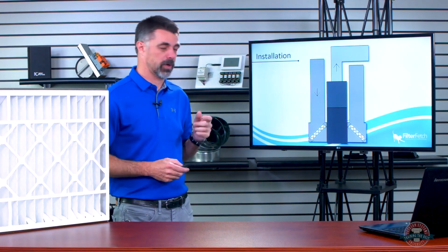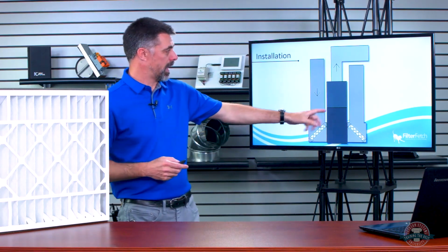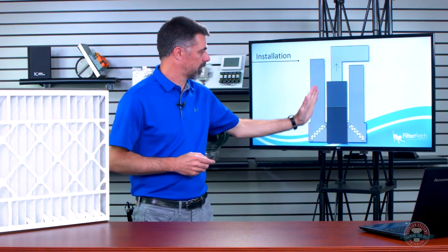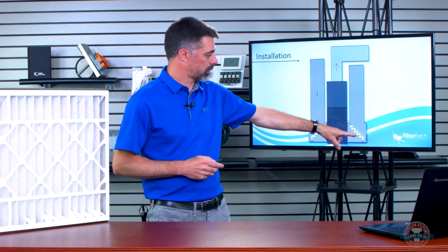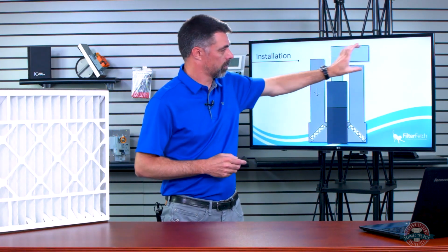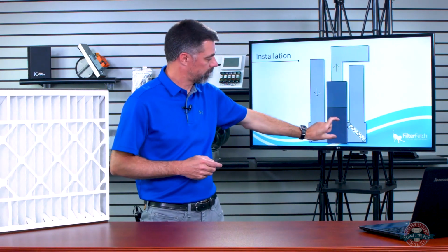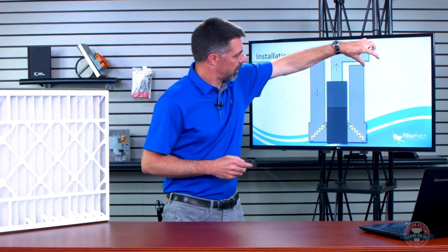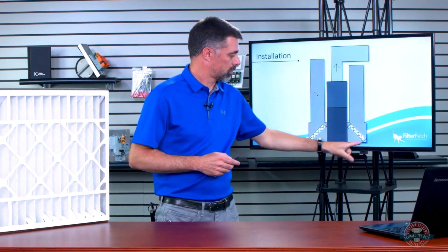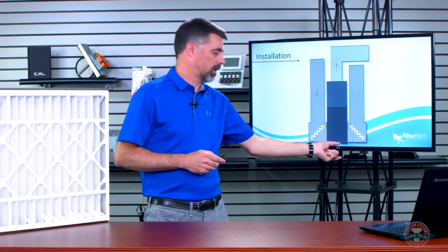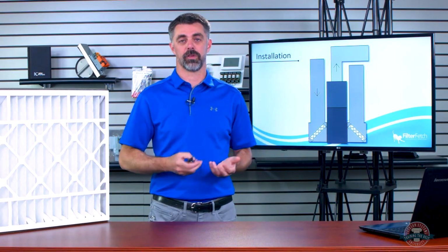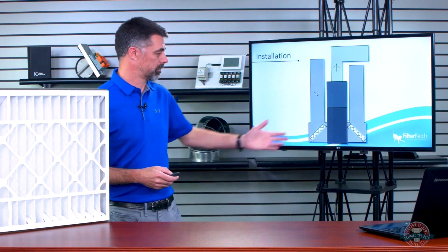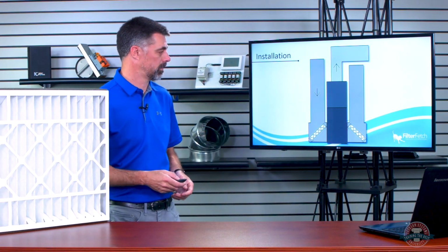I even had one job once where I helped a contractor out, and we only had space to bring stuff down on one side. This side had a wall on it. So we set the furnace up on a box, and we had two of these right angles. We had two drops coming down from a big return trunk up here. We had one going into the side of the furnace, and then we set this up on a box and we had a drop come down. We had another right angle sitting down here with a duct coming off of it going into that box. So there's a lot more stuff in there depending on the physical space that you have with what you can do. Sometimes you have to get a little creative, but you need to make sure you're getting the air into the unit in a proper fashion and enough of the air.